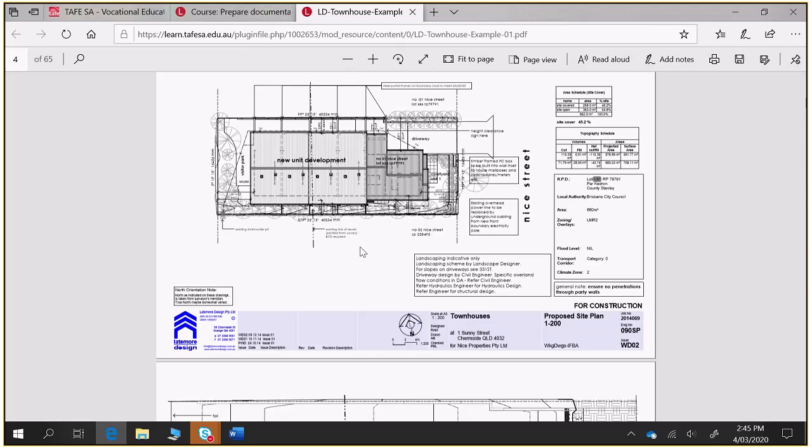And you might want to say measures taken to ensure no erosion. Yeah, that's what I was just thinking about. It's always going to be far simpler if you run your stormwater to the street water table, because then council know, stormwater to street water table, it's a downpipe popping out at the gutter. And so they won't expect it. If you're just discharging to the rear, they'll probably want to do a site visit and they'll want to assess the impact of that.